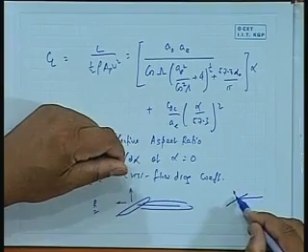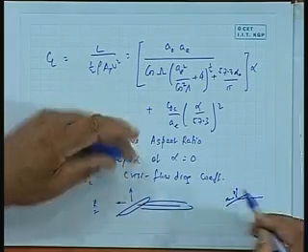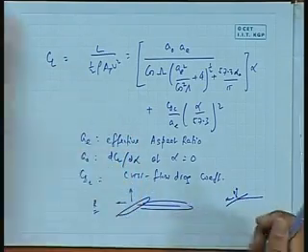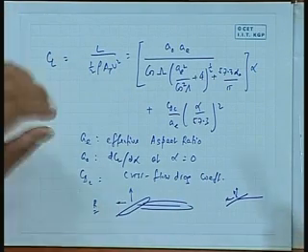For a long time in boats you had simply a plate, because a plate is also an aerofoil section with an angle of attack. If you simply take a flat plate, it will also produce lift and drag. Lift will be much less, and so it is less effective. That is why we use aerofoil sections. But this ordinary plate is very common. You can find it in your country's ports. Just put a plate there.